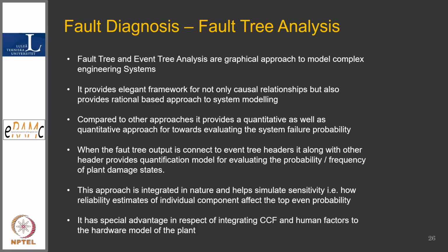If I have 3 redundant systems and I put them in one locality, then if a flooding situation comes, all the 3 will fail. So engineering and safety science has evolved to the extent that one will be located at a higher elevation, so that a level rise will not affect all the 3.